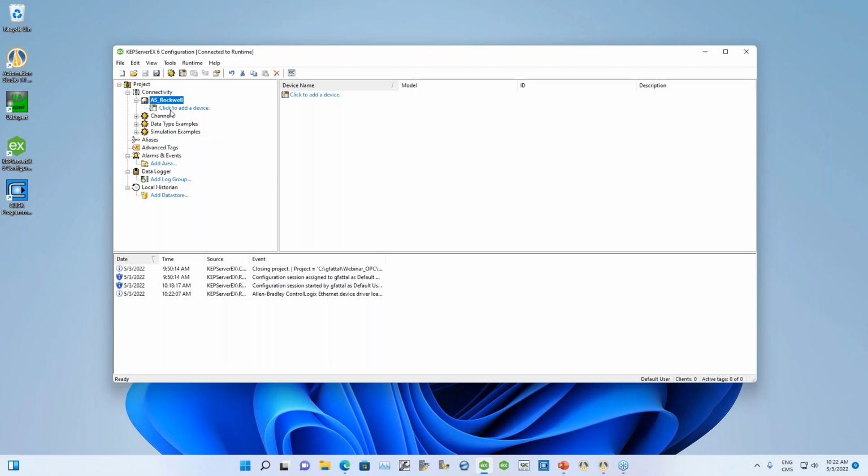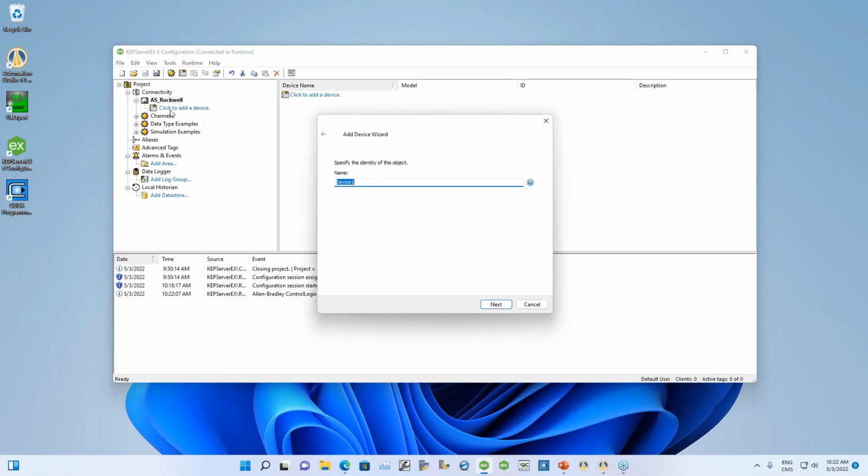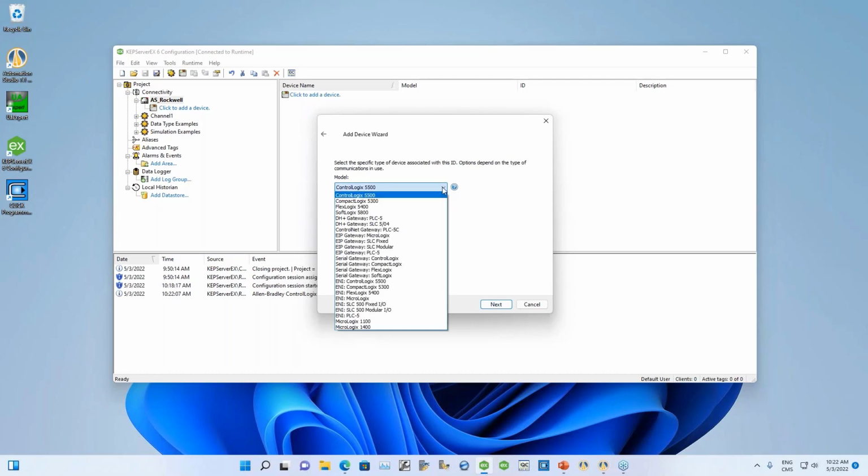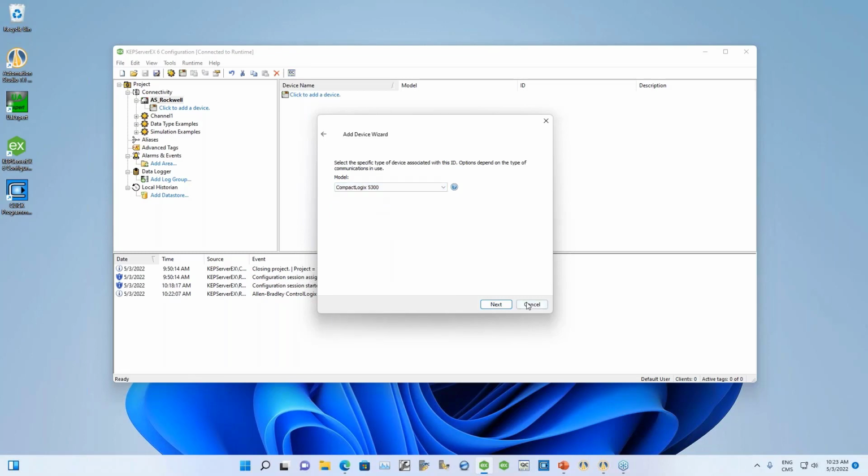Now the next thing is, for each PLC that you'll communicate with, you have to give it a name. For the templates that are available in Automation Studio, you have to stick with the name of this PLC. So I'm having PLC1 here because this is the first PLC. Now, after this, it asks you the type of Rockwell or ControlLogix PLC. For us, it's a CompactLogix, so you have to select the PLC that you're working with, CompactLogix, for example, 5300.